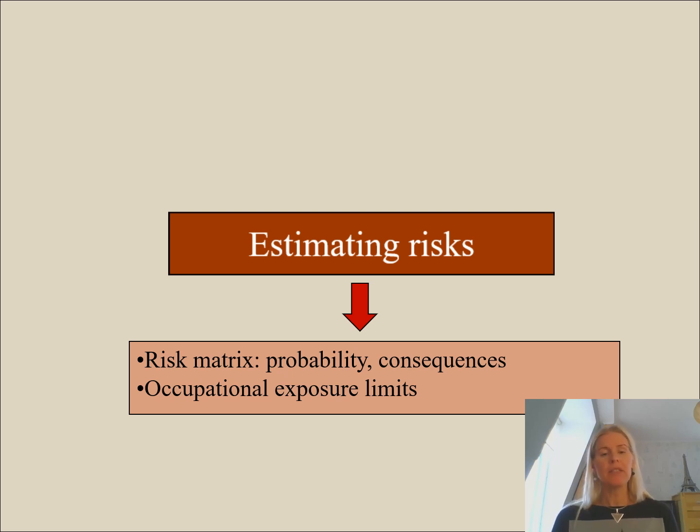For the measurable hazards, probably occupational exposure limits are set by countries. So to estimate the risk, you also need to follow the regulation and find out whether there are occupational exposure limits for those particular hazards. For instance, noise has an exposure limit of 85 decibels for 8 hours. So if you measure in your company and the value comes, for instance, 88, then there is a problem and the risk is high for the employee to get a hearing impairment. The same goes to chemicals, vibration, electromagnetic fields, and so on.